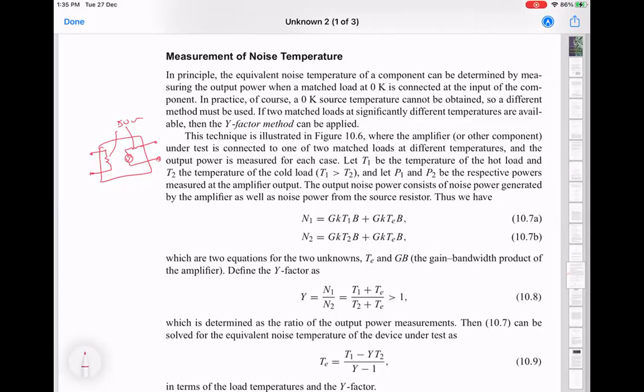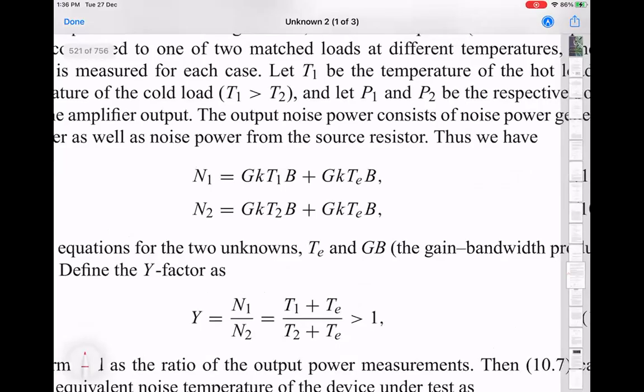So when you want to measure the noise temperature of an amplifier you have been given, how do you figure out how much noise it is adding? So usually you need something whose noise power you know precisely. And one thing, especially for experiments which are happening in cryogenic settings, or even if not, is that because of this equivalence of temperature and resistance, temperature and noise, you can use temperature as a source of calibrated noise. So that's basically what it's showing you here.